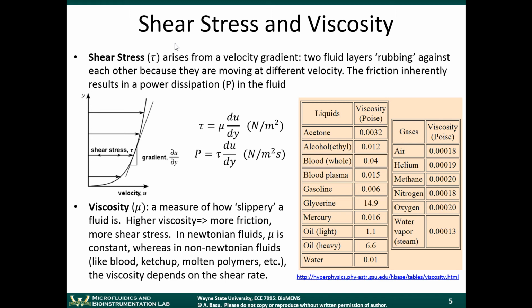This is the case at the macro scale. It's also the case at the micro scale. For the velocity at the channel wall, we say it has a no-slip boundary condition. If that's the case, then the velocity is 0 there. So let's say this x-axis represents y equals 0, the wall. The fluid velocity there is 0. These arrows are showing the fluid velocity. Velocity here is 0, and as we go away from the wall, the velocity increases like this.